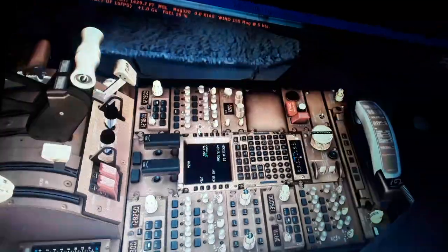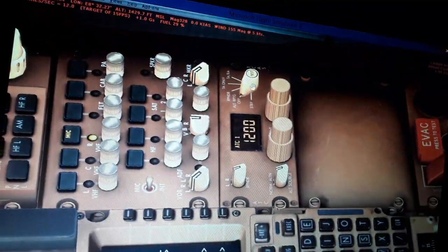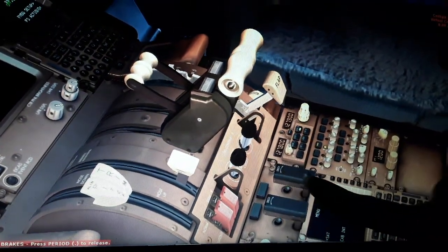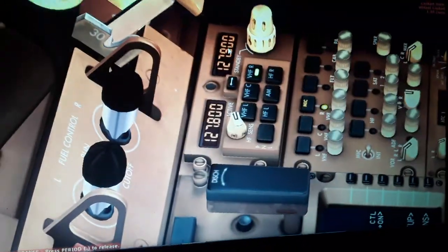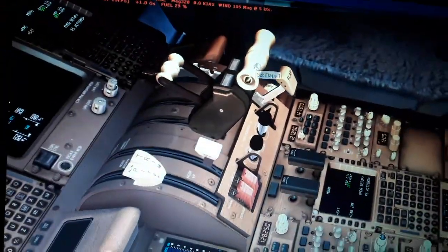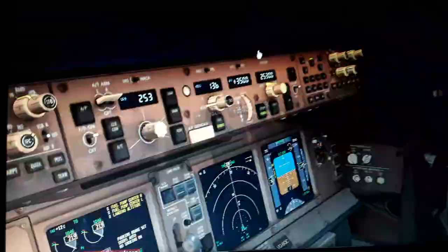We have the TCAS system, the traffic collision and alert system over here. You see and see other aircraft. You have the weather and terrain reflections, the weather radar. Now will come the left and the right engine. You see we have the left engine fire extinguisher and the right engine, and we have the fuel control switch, the left and the right in the run or the cutoff positions. Also later when we start the engines, we have other things to show you around here.